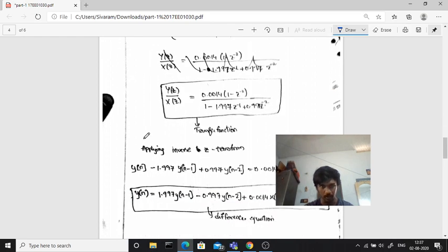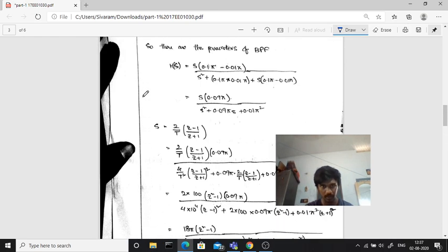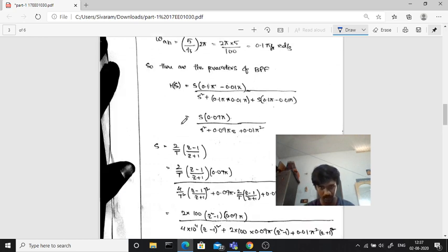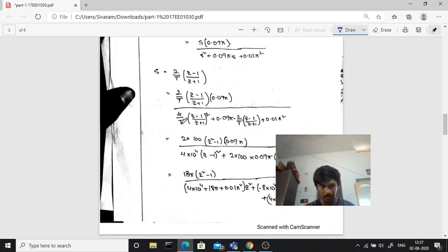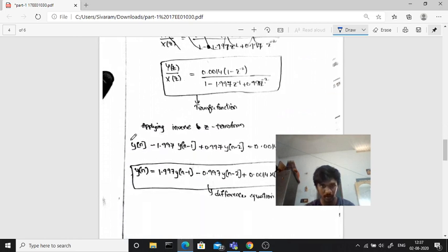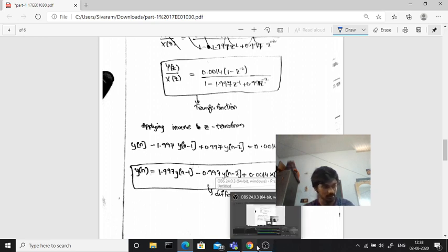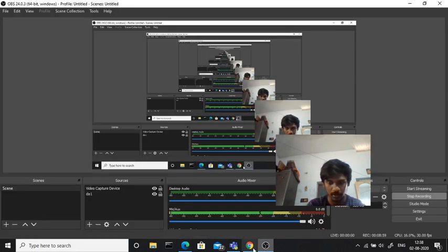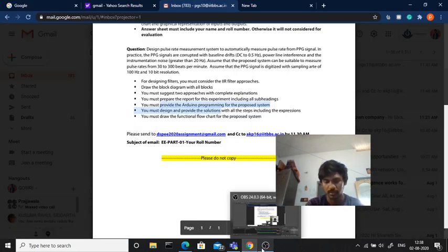in paperwork and so on. Coming to the explanation of this, we have the first transfer function H of s, and then we apply the lower and higher frequencies that we need to apply to the transfer function. So after applying the band pass filter, this is what we have applied. Then we need to apply the autocorrelation function and the zero crossing point to find the time period. And once we get the time period, we have the frequency formula, that is equal to 1 by time period. Then we can find the frequency.